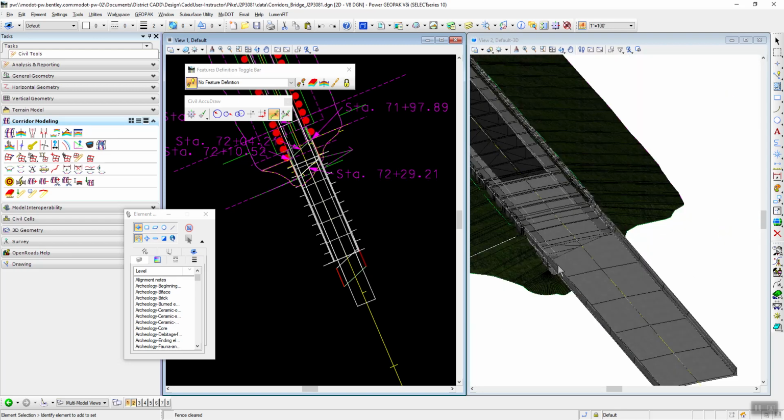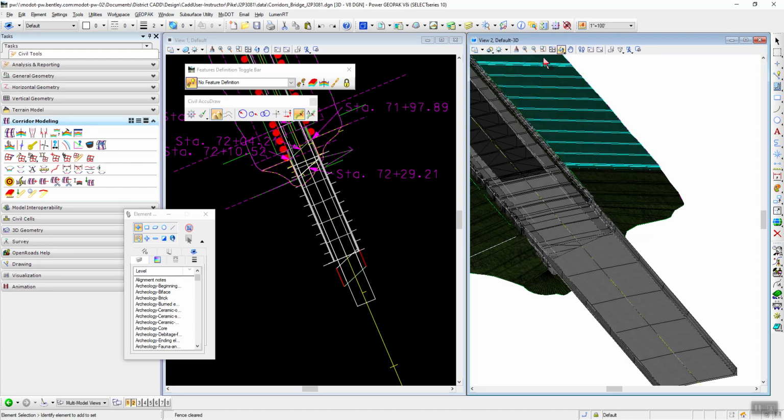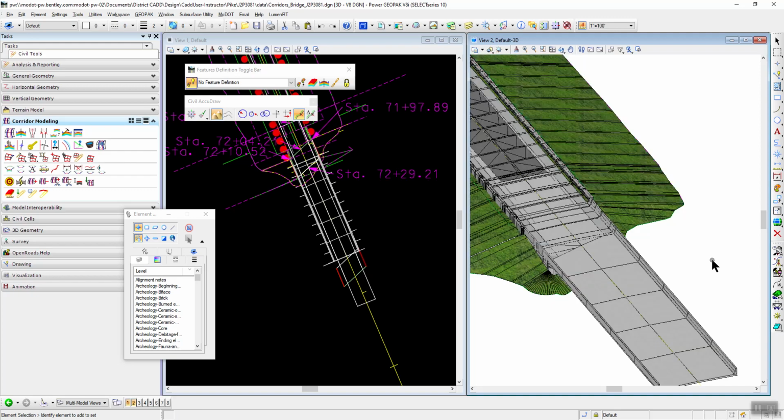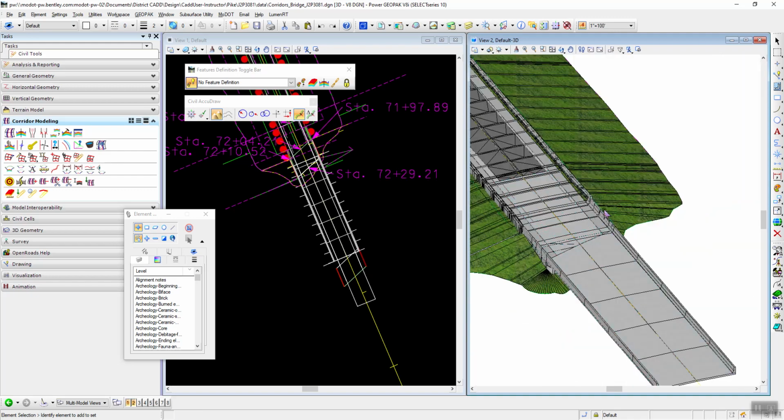We're going to take care of that the same way we did with that little piece that's hanging out here. We're going to create a little corridor clipping area, and it's going to clip out that bridge area back in here. So that's no worry. I'm going to make this side a little bit brighter. It looks a little dark on this side, so I'm going to go to the display and make it a little bit brighter, so you can see what's going on.